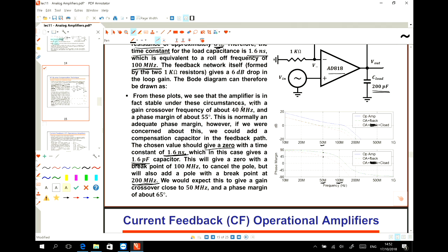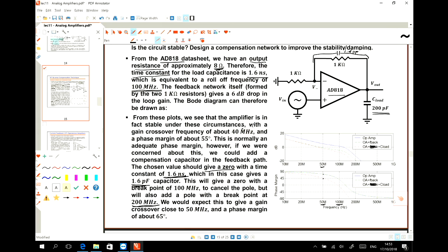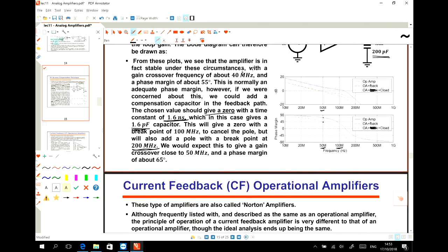If by adding a load to this system, the phase of the system drops or lags by, I don't know, alpha degrees, then if our phase margin is less than that alpha, the phase drops to zero and the system is going to be unstable. So a higher phase margin means that we allow a higher range of loads to be attached to our system while our system is not going to be unstable.